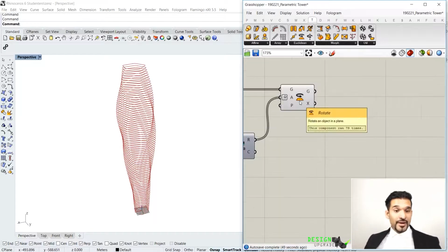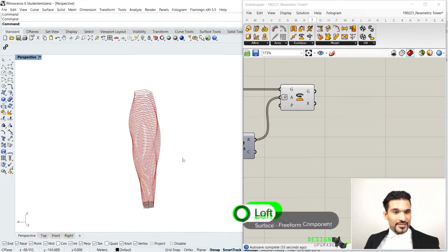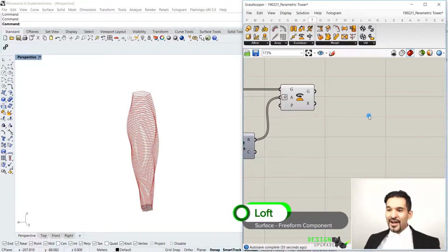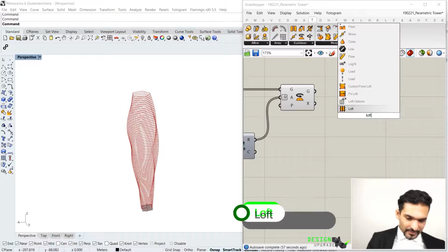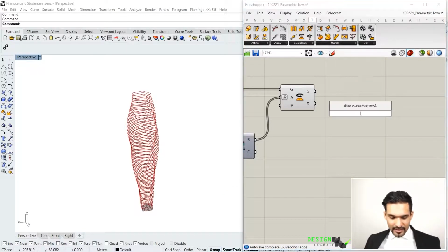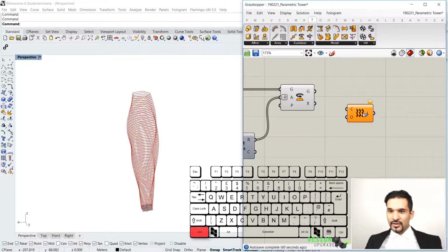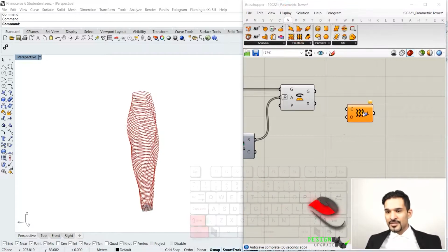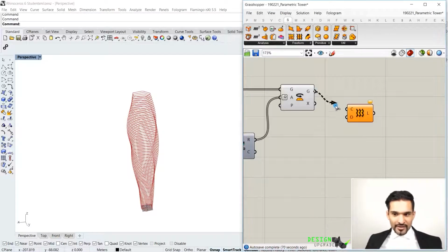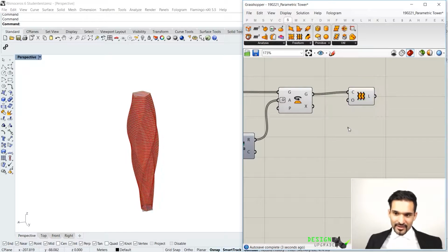And we can wrap it up by displaying now the surface. Right now, we are always looking at curves. This could be irritating. And we want to do that by saying loft. Take the loft command. And just again, quickly, that was too quick. Just type in loft. You will get the loft option. Control Alt mouse button is in surface. I hook up all of my closed curves, should be fine, and you will generate a surface.